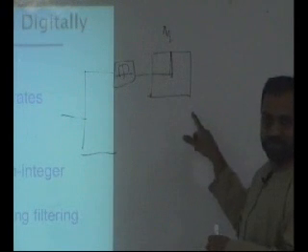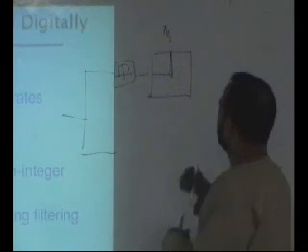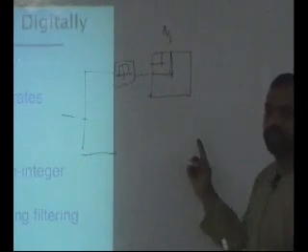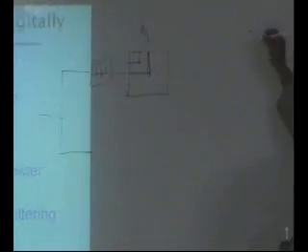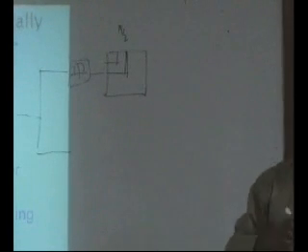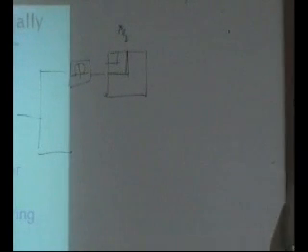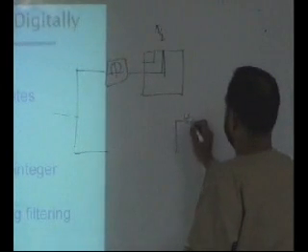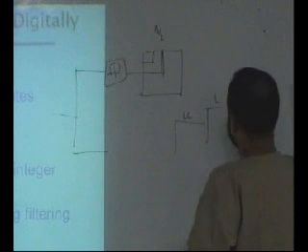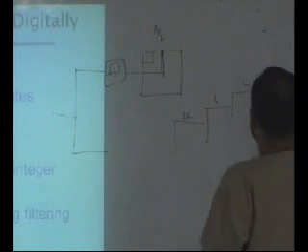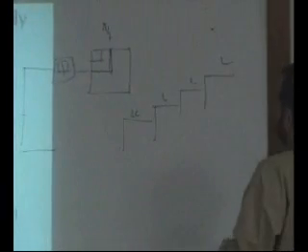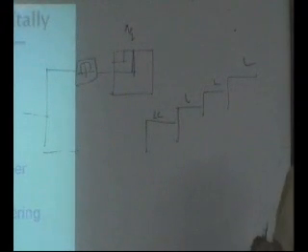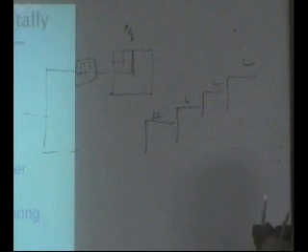Okay, so this is what is done in image processing, and then you take this and again pass it through a low pass filter. Again you throw away samples, again you pass it through low pass, and you keep doing this until you get a pixel, which is the most important pixel in your image, which is low. So you pass it through a low, and then again a low, and again a low. It depends on how many levels you want to do the decimation, and then this is the important leg of your image.